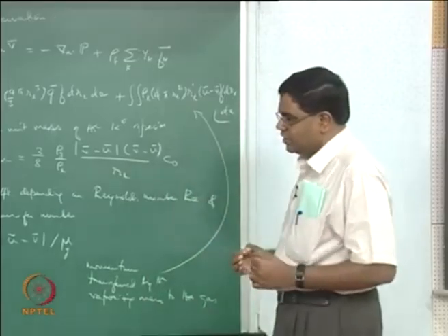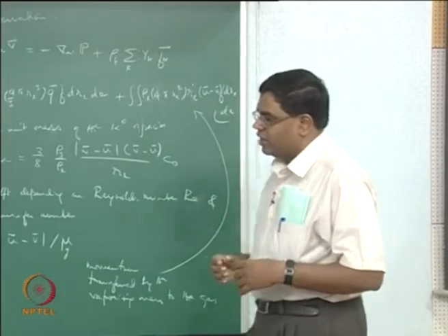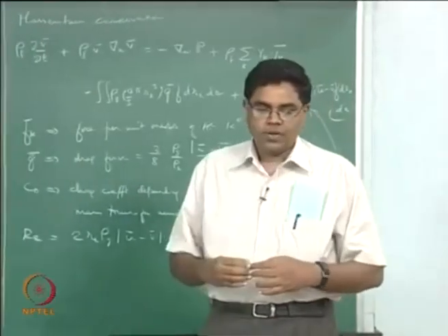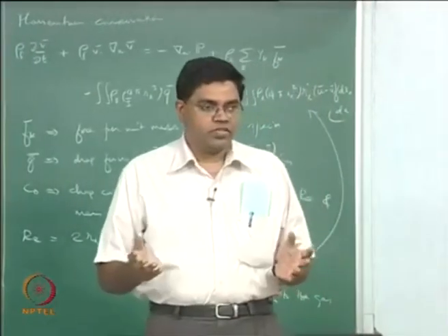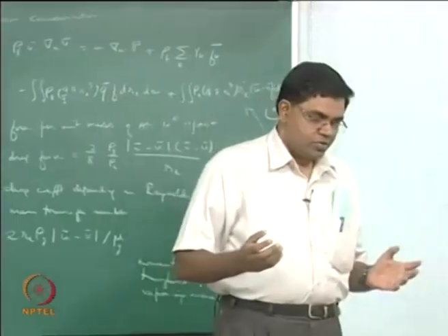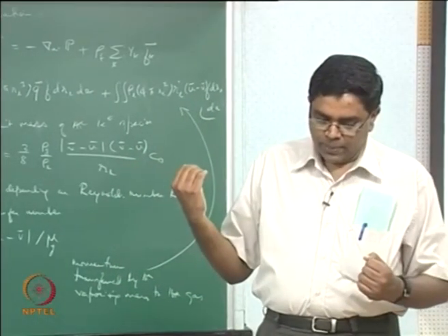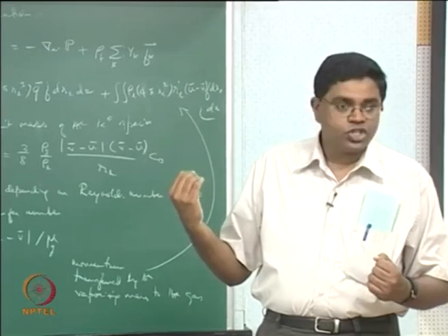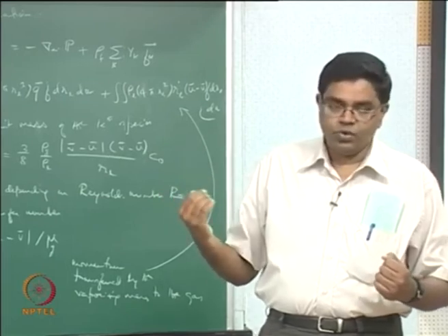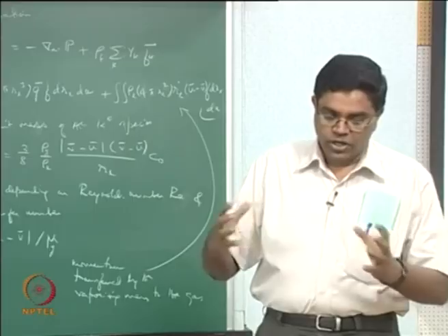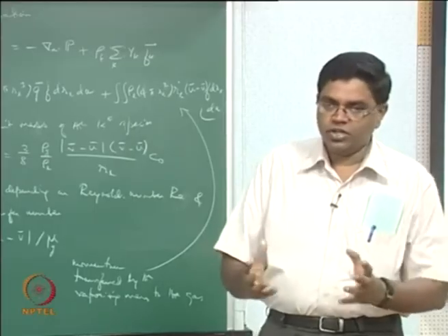This is pretty interesting. The other thing now, if you now begin to think about these droplets burning rather than just evaporating, and let us suppose that we were talking about the group combustion number, which now allows for individual droplets to have flames associated with them.